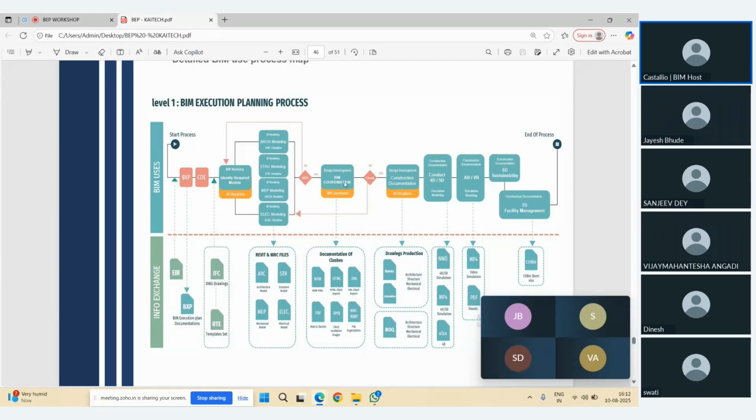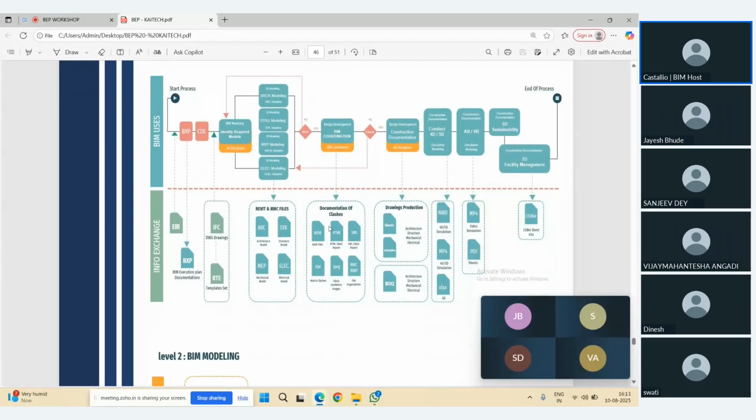Now you're working as a BIM coordinator. If some clashes are there, again you will send them to the modeling team, right? You can see here the check. The same thing will be happening here, but here you are checking the clashes, while here we are checking the model quality and quality assurance. Even we could say some design norms, meaning whether the modeling is as per our standard or not. In Germany or in the Middle East, there are some model standards available. So this is the purpose.